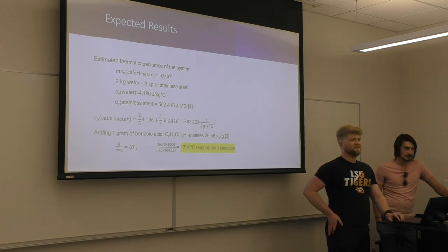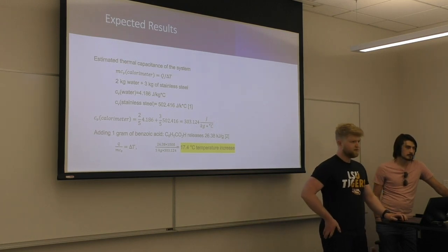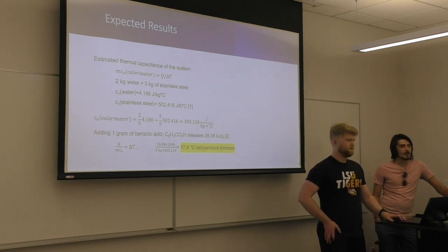I'm not sure exactly what it's going to record, other than, I mean, we're going to record the temperature of the water. You have the thermocouple in there, right? So what does the thermocouple record? Yeah, the change in temperature. So you should see a significant rise in temperature when the bomb ignites. Yeah, that's how you know it's ignited. If not, you have to do the entire experiment again.